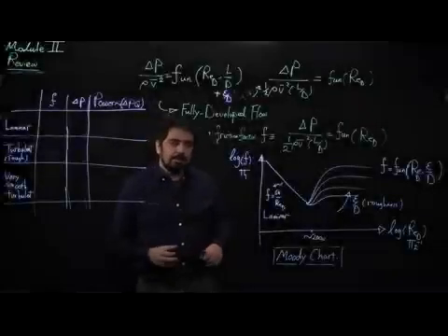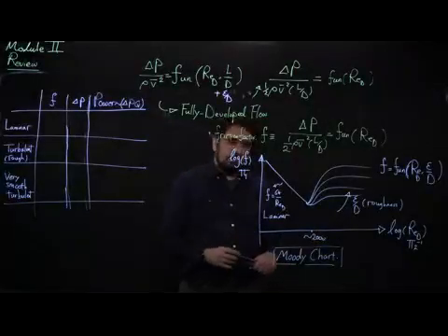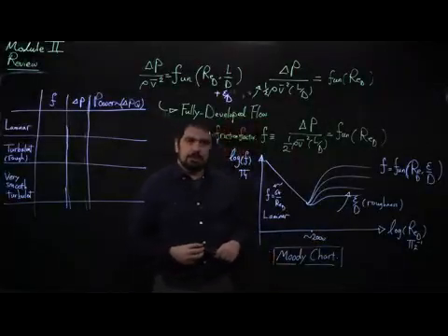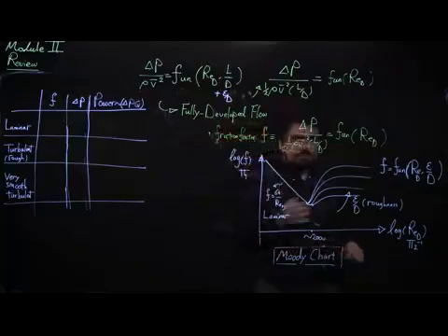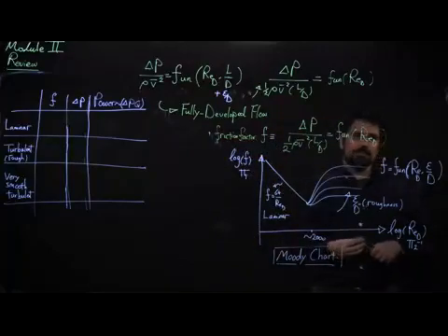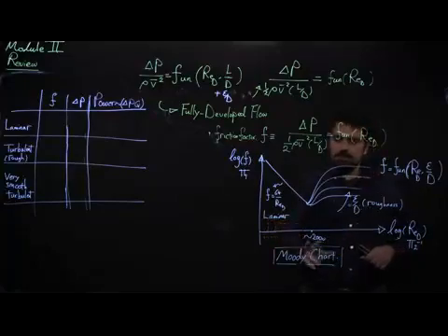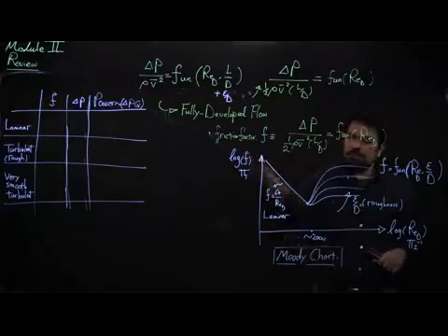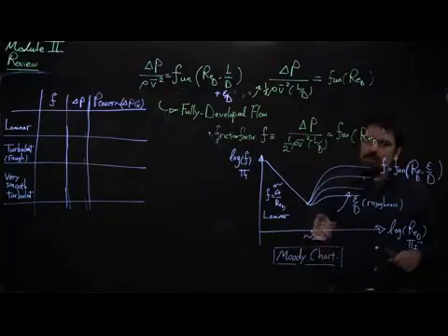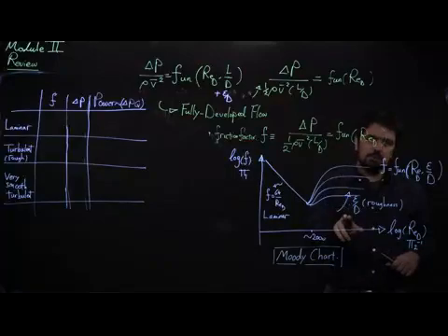Hi again. We finished the last video with the concept of the Moody chart and mentioned that there are certain interesting phenomena happening in terms of pressure drop when you have flow in an axisymmetric pipe. There's a laminar regime below Reynolds numbers around 2000 where the friction factor is inversely proportional to the Reynolds number. When you go to the limit of turbulent flows, you get different solutions and different curves depending on the roughness ratio that you have in the pipe.